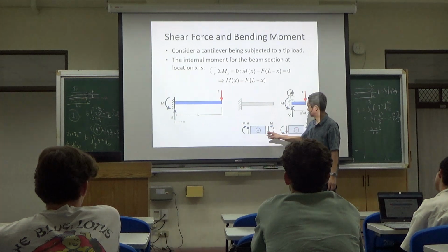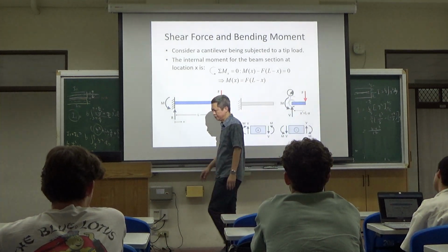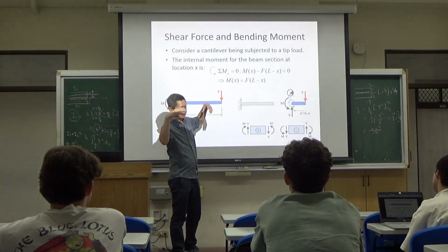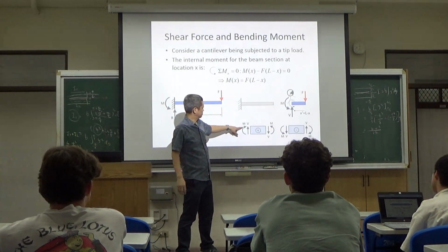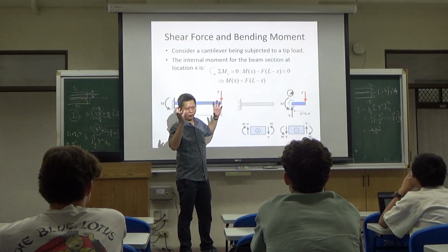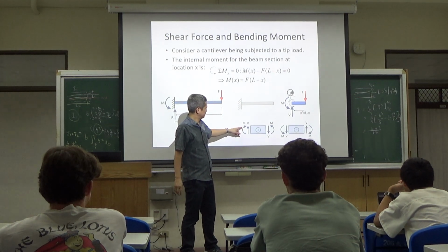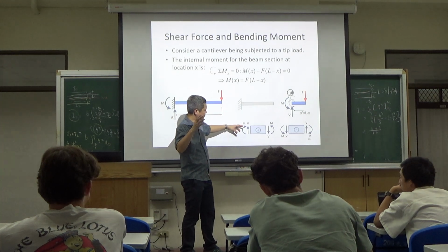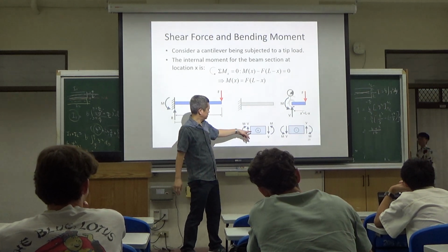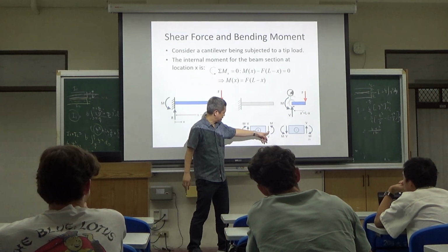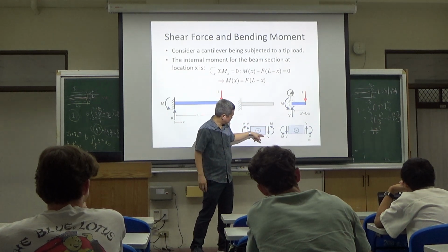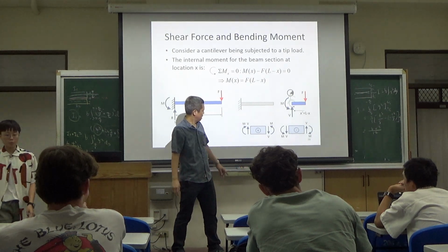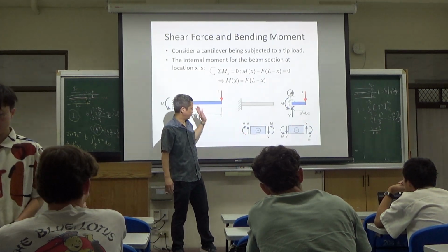So let's take the conventions traditionally used for mechanics of materials. A smiling curve corresponds to a positive moment. This is a convention that takes account of the zero moment sum. Likewise, this smiling curve will have the shear force on the right hand side pointed down and the shear force on the left hand side pointed up.